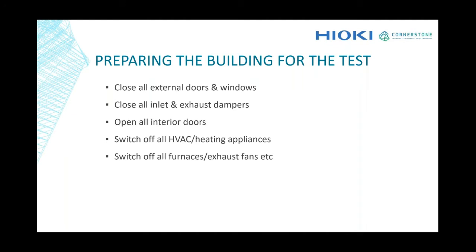And also the inlet and exhaust dampers of the HVAC are closed, and all the internal doors are open in order to maintain a constant pressure level inside the building. The HVAC units are closed, and if you have any furnaces or exhaust fans, everything is closed.